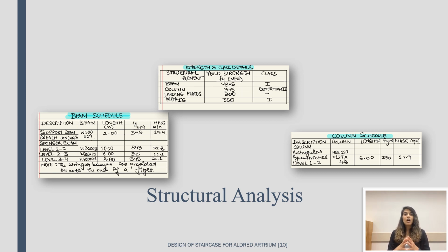Going ahead with the column design, only a single column is provided at the intersection where the landing is connected to level 1. This column is only provided to give extra structural resistance to the structure. A rectangular HSS was not opted for in this structure since the installation of a square HSS is way simpler than installing a rectangular HSS.